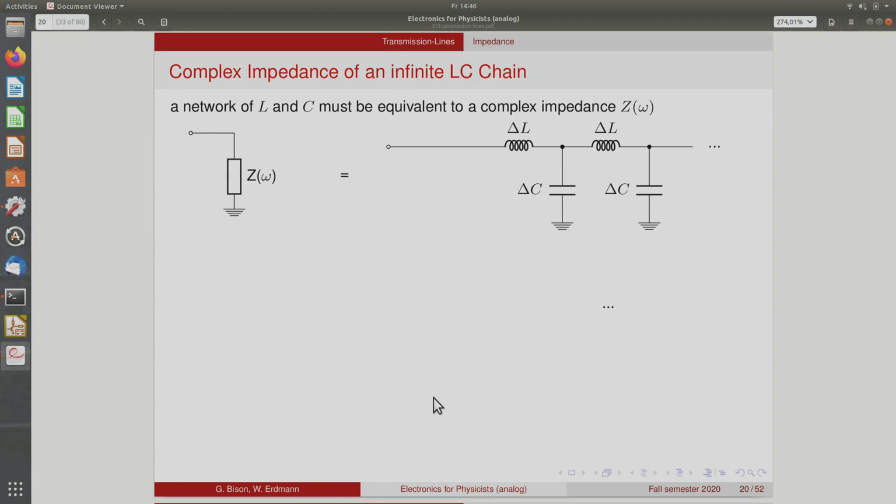If you go to really infinitesimally small LC segments, then the transmission on a transmission line would be without any distortion, would be perfect, okay? The reason that we don't see that here is that this is not a transmission line, because there's no second conductor that allows a constant cross-section along the path of the wire. This is completely undefined inductance and capacitance, and it changes along the cable. So this is just not a transmission line. That's why the transmission is not perfect. If you do the same thing with a coaxial cable, you would get perfect transmission. Okay. So this point is important.